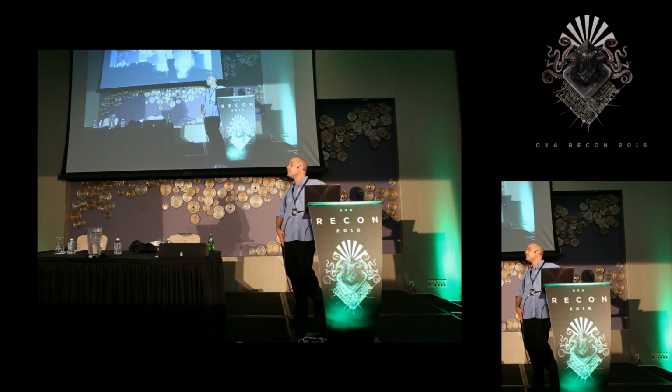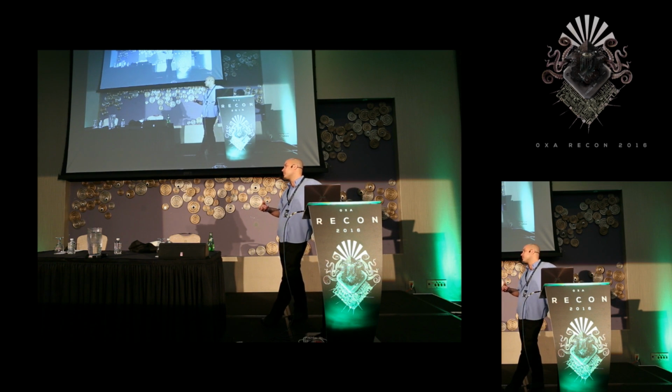For the main transport stream or for the out-of-band transport stream? Okay, for the out-of-band transport stream, I wrote some software that did the de-randomization of these things on the raw transport stream because I was getting it directly out of the QPSK demodulator. For the main transport stream, all the demodulation is done and complete before it goes into the ACP. So it looks like a normal transport stream, just encrypted. So after the software decryption, then I could feed it right into VLC.